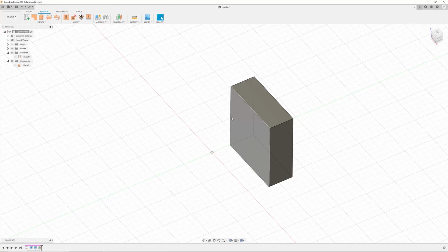The best way to describe that is between two points is going to be a line. A closed network of those lines is going to be a surface. A collection of multiple surfaces is going to be a polysurface. And then when that is fully enclosed, that will actually make that a solid. So that's the difference between those two.